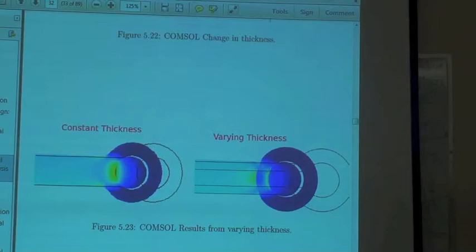That's a good point about optimization. So you're doing it manually by just going and changing the thicknesses. Yeah, but like you said, you could do a parametric sweep where the thickness of this whole thing is just a variable, and then you can look at the contact stress.